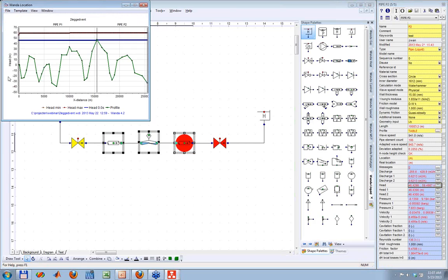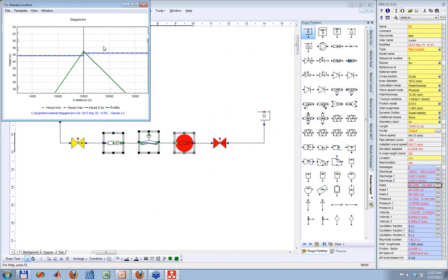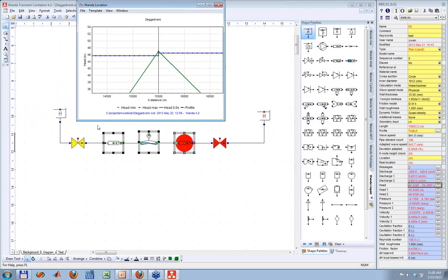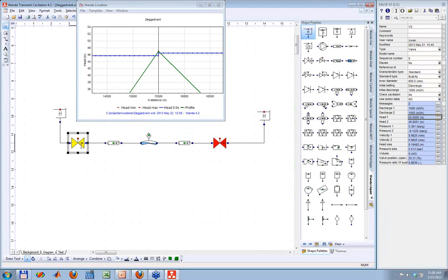And as you can see, this is the highest point, there are some more local high points, but at this moment I assume this is completely filled, and only here in this part, if I zoom in you can see it better, some air remains, which needs to be expelled. And basically that is done by the pumps, which are modeled as a constant head reservoir, and have here a valve which is throttled to a certain flow rate. So what will happen then?